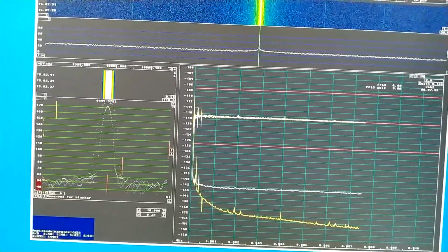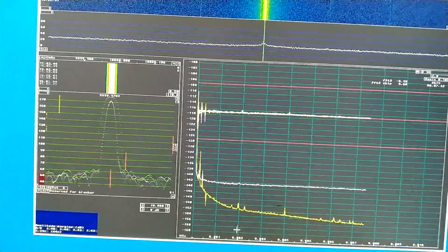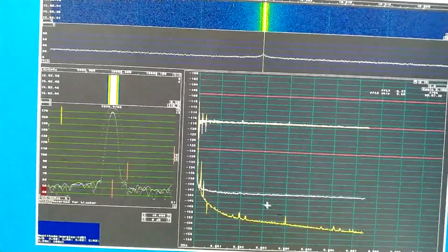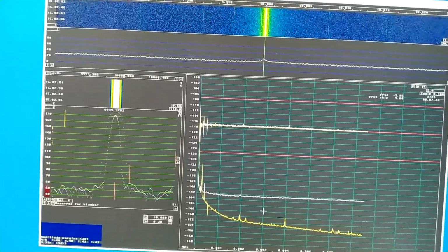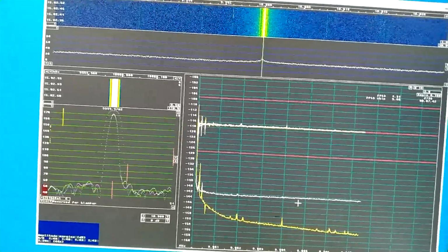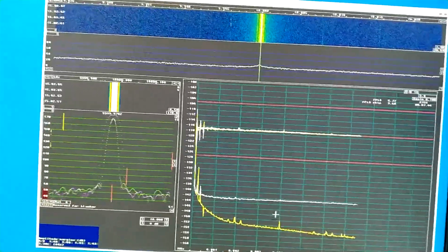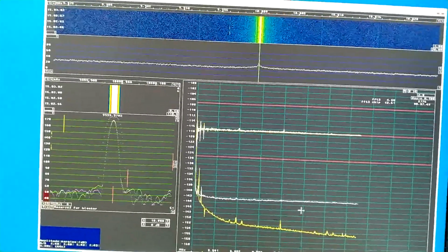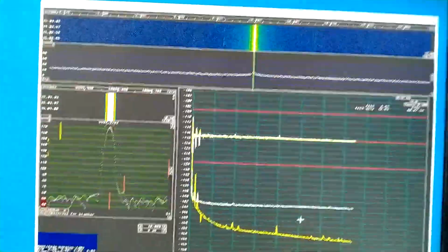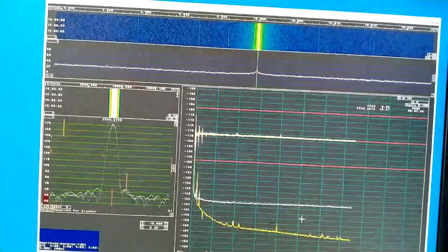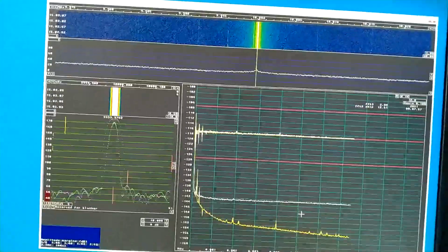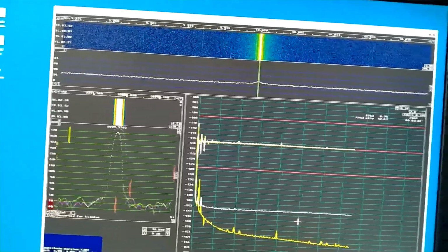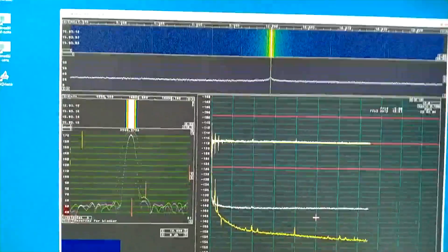That should give an improvement at all frequencies where there is a correlation. And one could also use that same signal to produce amplitude modulation that would cancel the AM noise also. So there is a scope to make a much better oscillator, at least at wider frequency offsets, by adding such a system. But on the other hand, better to choose another oscillator that doesn't have this kind of problems.